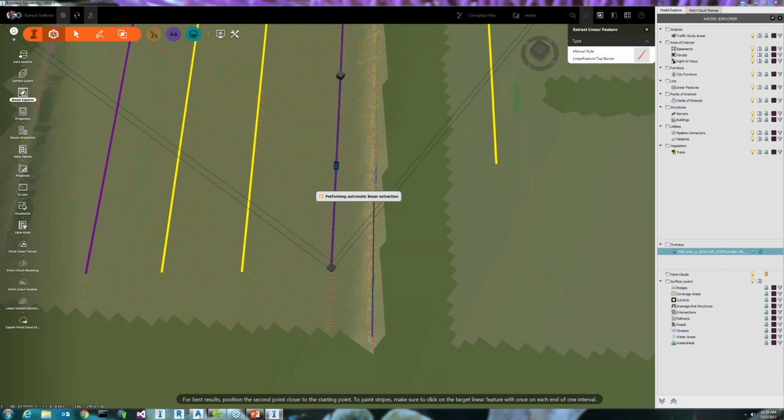You can make sure you get the best line work possible. Some customers like the top and bottom to be extracted in the cross-section view because they feel comfortable that's the accurate way to do it. You definitely can. As a matter of fact, I will try to extract the bottom of the barrier in cross-section mode. But just to tell you, if you have a good data set like this one, then you can utilize some of the automated methods to get your job done.